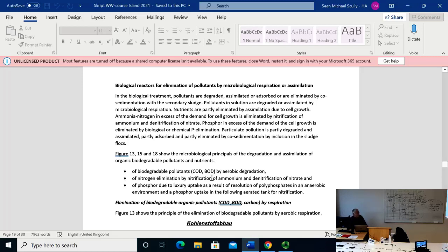Like we are in the aerobic degradation. This is what comes from the human. This is what is eliminated in the primary sludge. 1 liter, 40 grams of COD, 1 gram of N and 0.2 of P. That has to do with the sedimentation of the settleable matter. So what goes into the bioreactor is 80, 10, and 1.6.